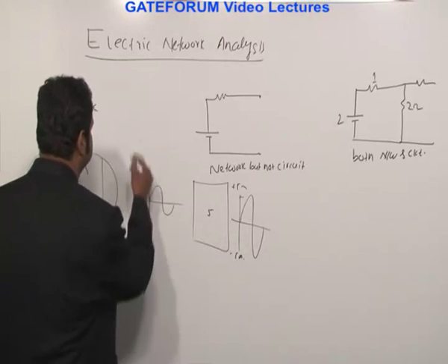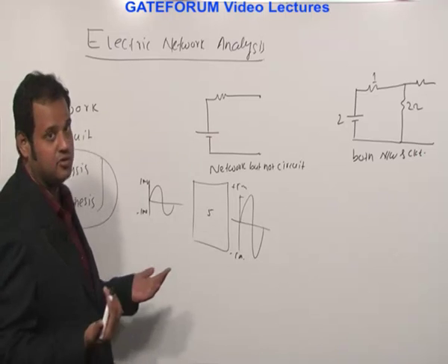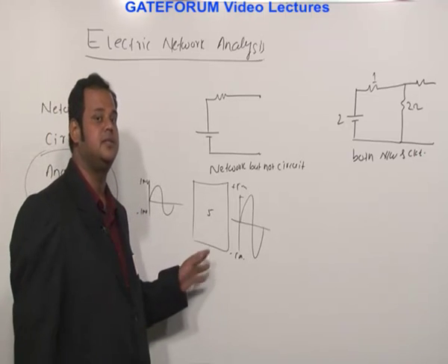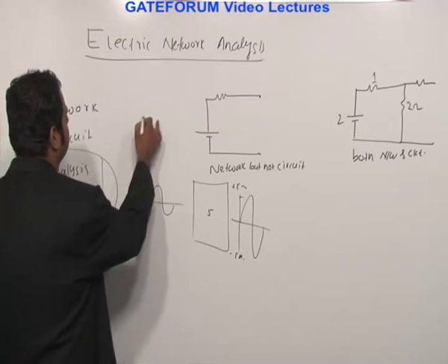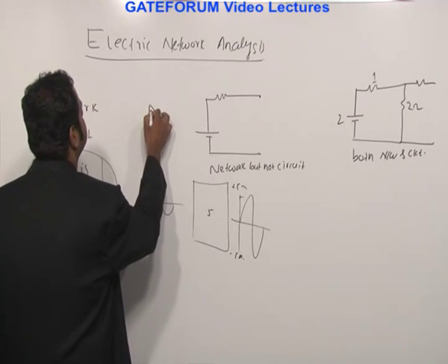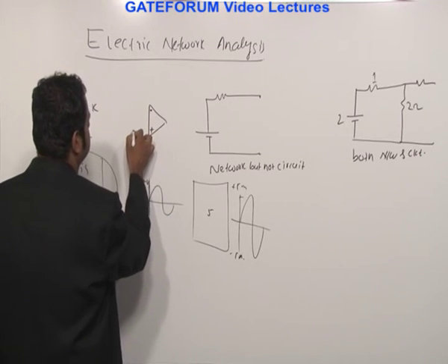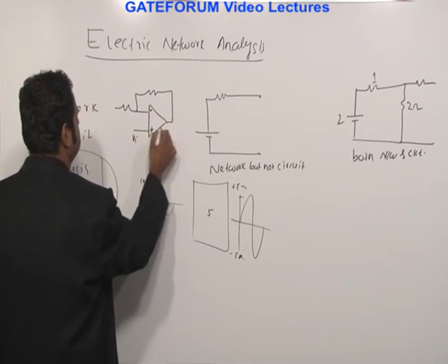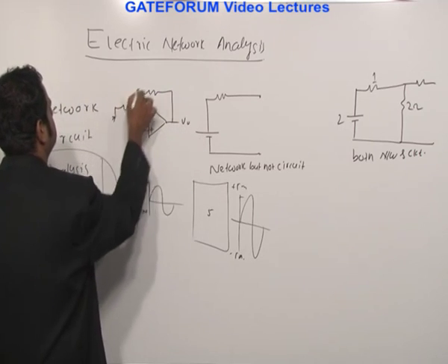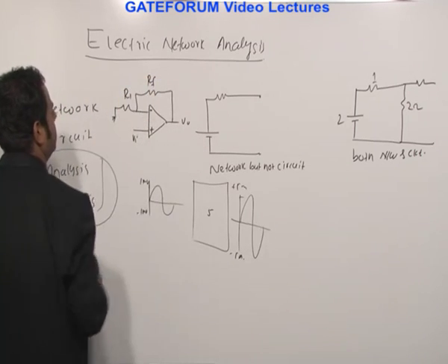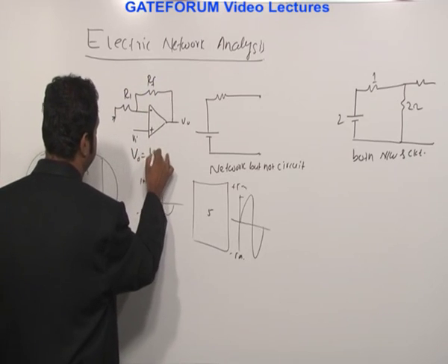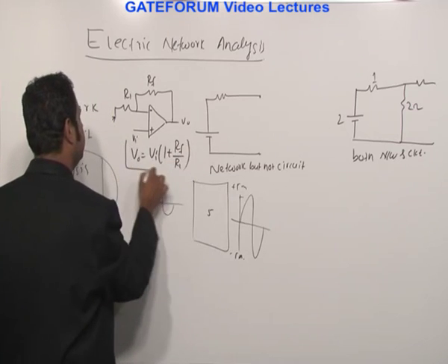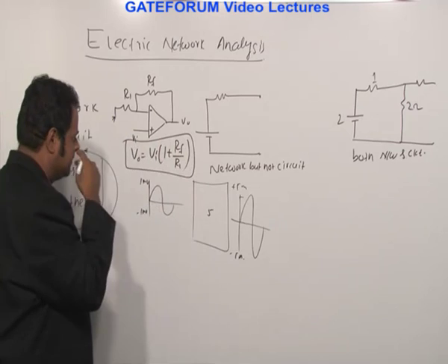Let's say that you are designing by op-amps. So what kind of resistor do you need along with the op-amp? What is the gain of the op-amp you need? Or do you need any capacitor kind of things? All those things have to be decided by you. See, for example, when I take an op-amp based case, let's say the non-inverting case, right? I can select this as Vi, this is V0, this is RF and this is R1. I hope all of you know that V0 is given by Vi into (1 plus RF by R1). That's the gain formula of this non-inverting amplifier, is it not?